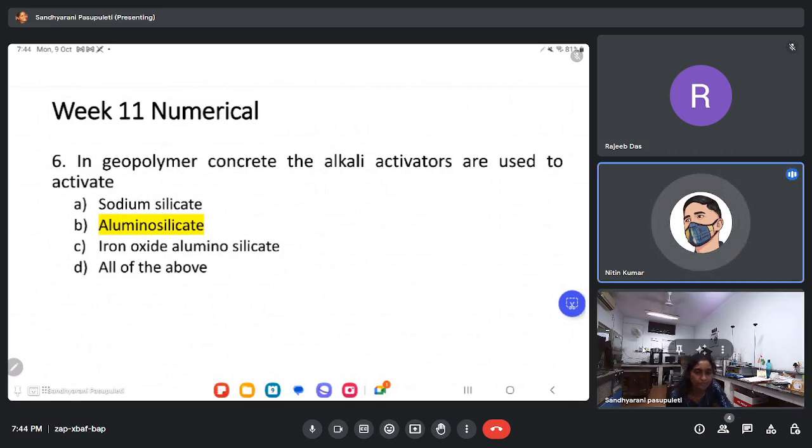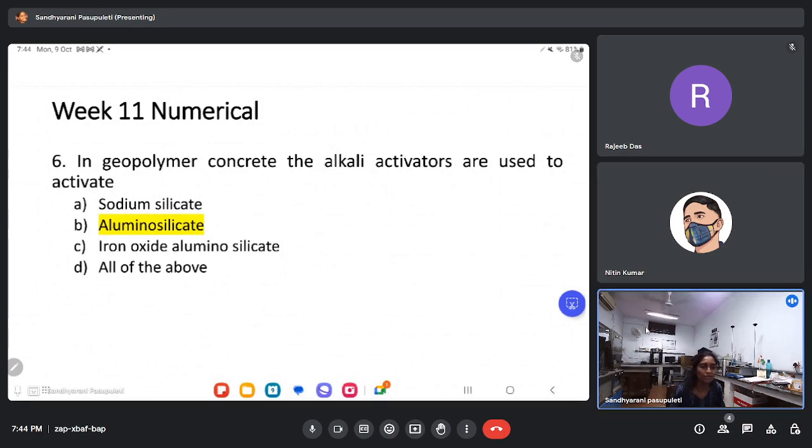Ma'am, what are the uses of PSC cement? Portland slag cement. These Portland cements or pozzolana cements are all used to avoid, first, environmental emission. Let us say in OPC cement we have calcium hydroxide, so we have an excess of it and we have to reduce that. If we add these pozzolana materials, they react with the calcium hydroxide and form CSH gels. Those gels actually give higher properties. That is one of the advantages.